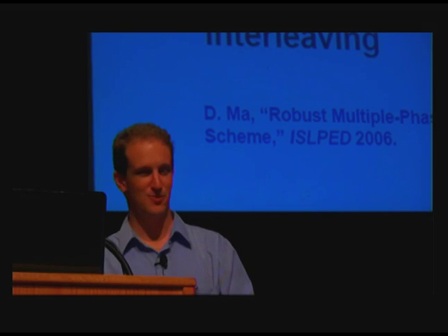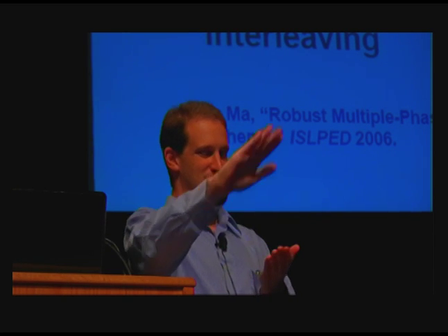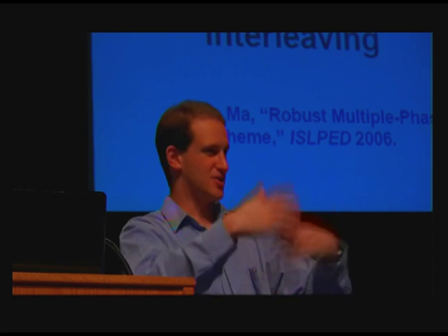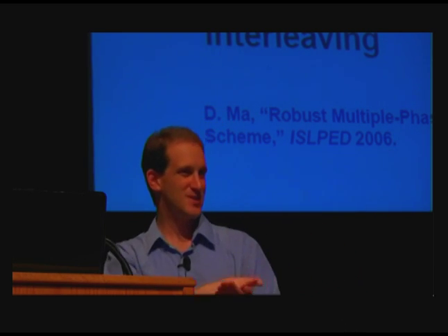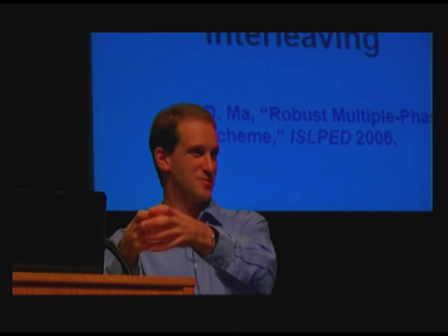Yeah, no. So let me maybe take a step back just to make sure that I understand the question correctly, and then I'll try and answer it. So when I quote that 0.86 or 1 watt per millimeter squared, what that means is how much power is delivered from the converter to the load, okay? Now, let's just make the numbers easy. If I had a 90% efficiency converter and I was delivering a watt per millimeter squared, that would basically mean that I'm dissipating about 100 milliwatts in the converter. So in other words, if I looked at the total thermal dissipation of the chip, if without the converter I had a watt per millimeter squared, then indeed now I would have 1.1 watts per millimeter squared. So does that sort of get at the question that you're asking?